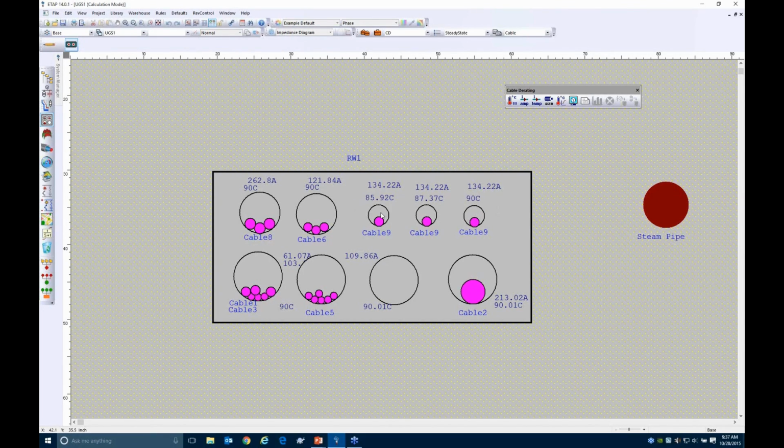So what this number is actually giving me is the value 262 amps, 120 amps. This is the maximum capacity of those cables, such that all the cables within this system are at their maximum temperature limit. So I can essentially pass 120 amps through cable 6, 262 through cable 8, and that's the maximum limit of current. And both of them will basically reach their temperature limit because they depend on each other.